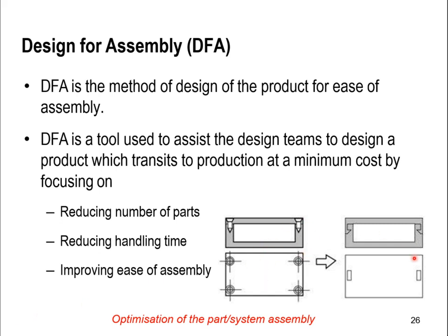So you can see the difference between the two photos here. What's happened is that earlier we used to have the screws to hold the parts together. We just changed it to a snap fit. That's it. So instead of spending like 10 seconds or 20 seconds trying to put the bolts on, we're only going to push it once and that's it.